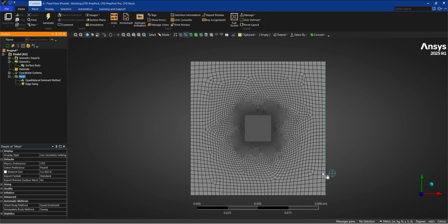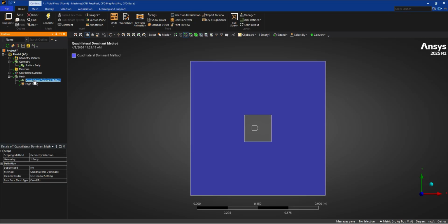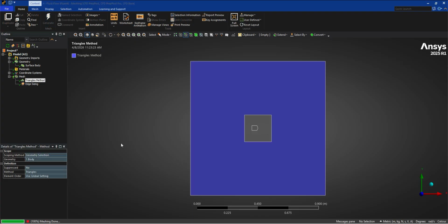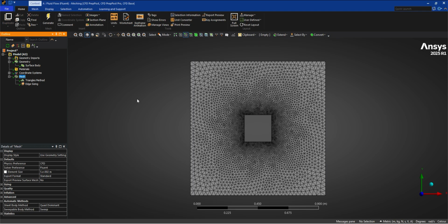So the mesh is better, but we do see a lot of inconsistencies still. I suspect if you make the growth rate smaller, closer to 1 essentially, that should fix the problem even more, but we want to make things easy, so we go to triangles instead of quads, and we're going to see that we're going to get a much better mesh with the triangles. See? We see some problematic areas, but these are not very dominant and important.